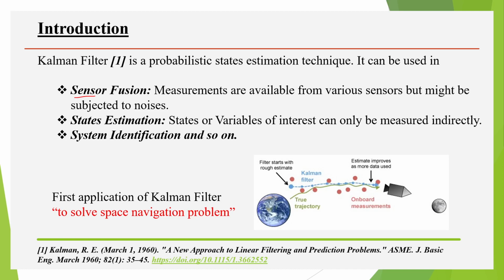But at the same time, we have another sensor on board that can measure acceleration, for example, an IMU, and then we can integrate it to compute the velocity as well. So two types of sensor can be used to compute the same thing. So we can implement the algorithm to get a better estimation because all sensors are corrupted by noise.